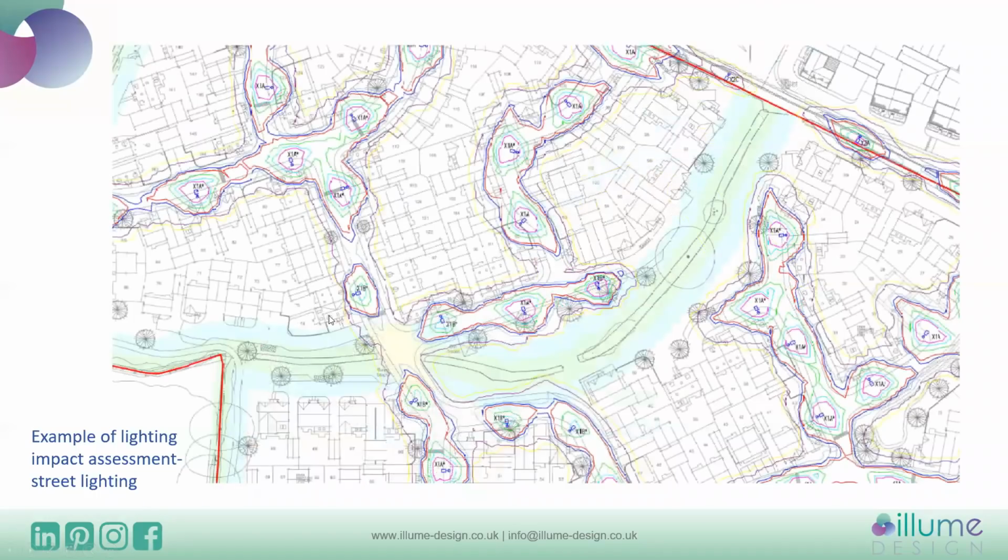So you can see more clearly at the crossing point. As I mentioned before, we can move the lights to make them as far away from each other as possible, so the minimum level of lux is within that crossing point. So the darkest point is there, and we can design around that. And I think some of these luminaires were also dimmed, or their output was limited in order to achieve a lower level of lighting at that point.